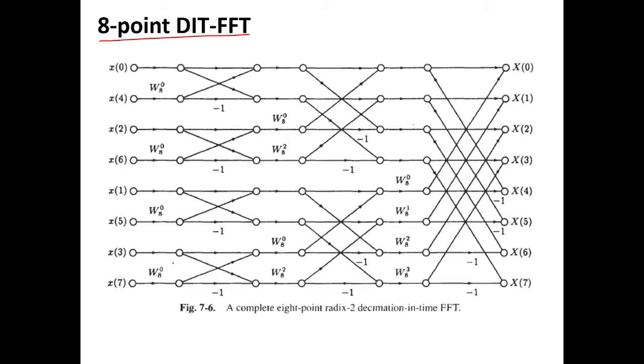But what I prefer personally is that suppose you are having W0 over here. We are performing 2-point DFT, so we can replace this W08 as W02. Everywhere we can replace it. When we are performing 4-point DFT, it says W08, W28, so I can easily replace it with W04, and 2 by 8 as W14. Why? It makes my life easy. When I am performing 8-point DFT, I can keep it as W08, W18, W28, W38.